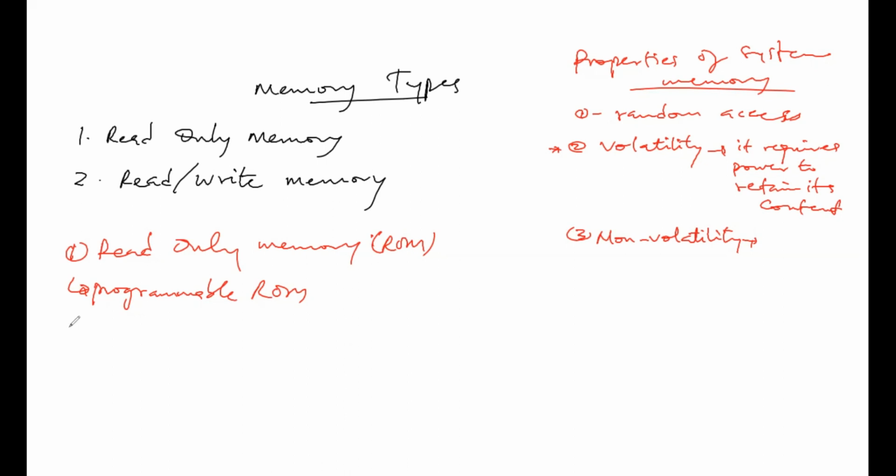That's for the programmable ROM. Then we have the erasable programmable ROM. Erasable PROM, EPROM, right? So they call this PROM, and they call this EPROM. So the EPROM offers further flexibility during prototyping, okay? So the contents of the EPROM can be erased by exposing it to ultraviolet light for a few minutes.